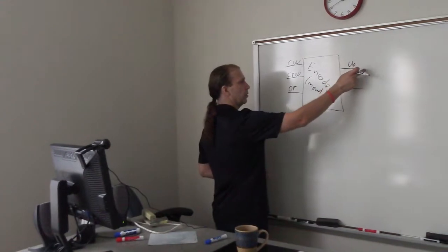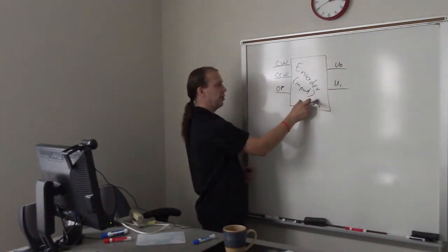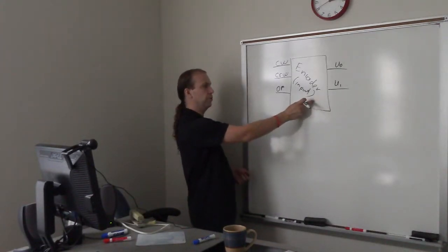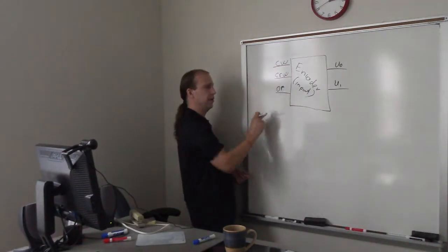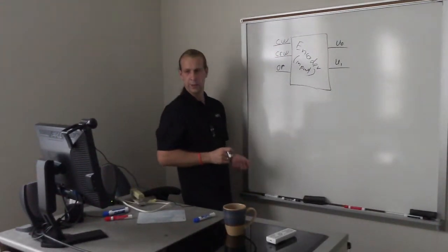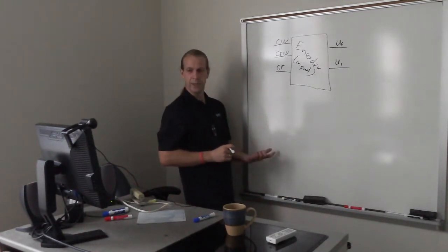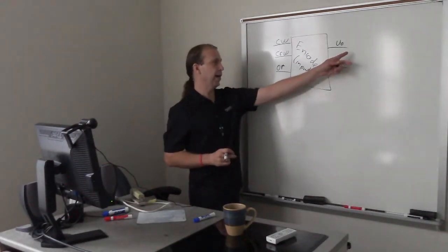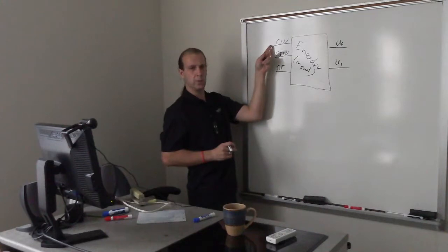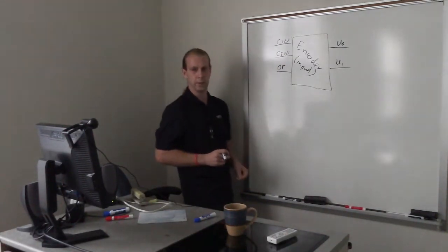So how do we derive the logical expression, or in other words the circuitry in this encoder, to generate U0 based upon the 3 inputs? What we need to do is draw a truth table, which will show our intent about assigning particular bits as a response to a certain combination of the input commands.